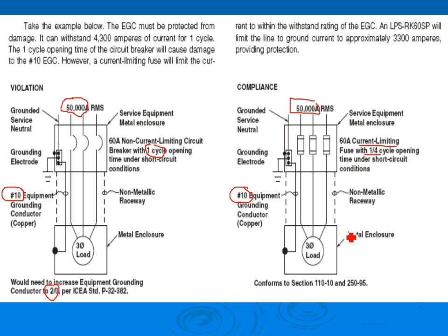Line to ground is typically half of line to line on the system, and it happens 85% of the time. So my advice is that on most of the systems you use 250.122 when you size the conductor. 99% of the time you're okay. It really is. If in doubt, what you really need to do is take the conductor, put it in the software, if you have software, and check it. But if you use 250.122, you covered it.